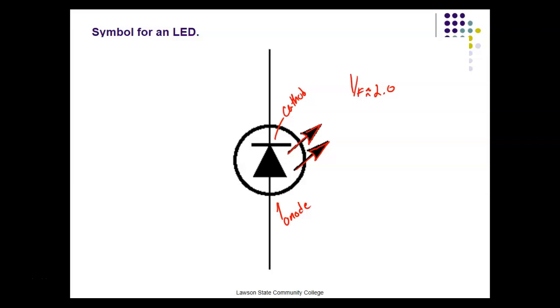On these diodes that we're going to be using, there's going to be a cap on them like this, and then they're going to have a little lip around on the outside. If we look at the lip, just the lip, we'll notice it has a flat side on it. And then the leads are going to be on here, and the flat side identifies the lead that's the cathode. And also, if you look at them, you'll see one of the leads is shorter than the other. And the short lead identifies the cathode.